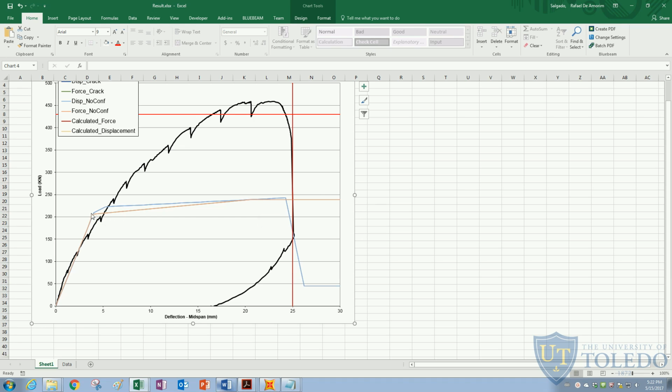Another thing we can see is that using elastic elements with nonlinear hinges, such as the SAP2000 model we have here, gives us a very rudimentary response. Like we can see, it's basically just a constant stiffness up to yielding, and then a constant stiffness up to peak, and then it fails. A fiber-based frame element, which can consider distributed plasticity along the element, would give us a much better result and a much closer fit to the experimental response than the model we have in SAP2000.